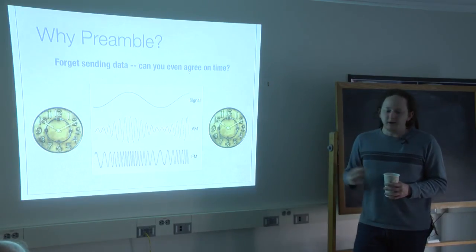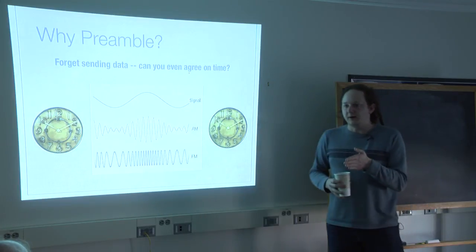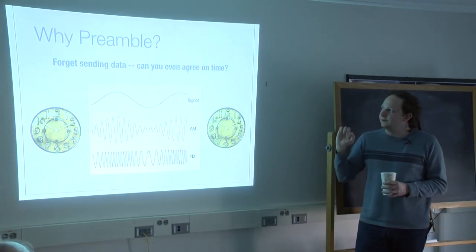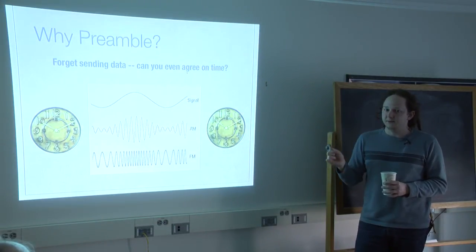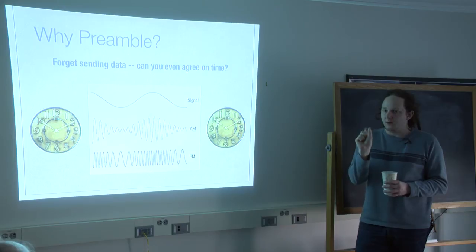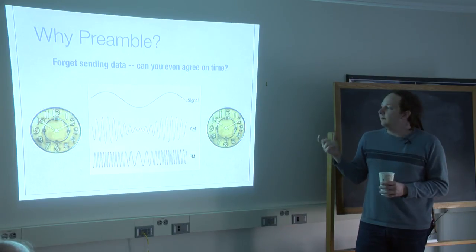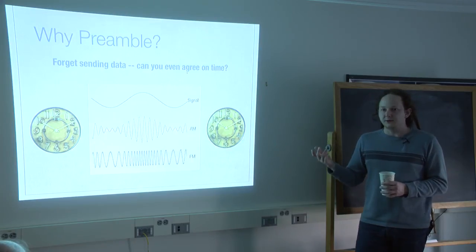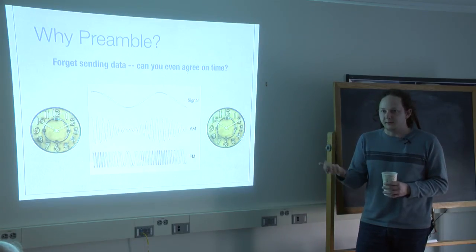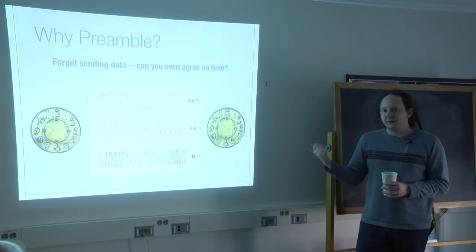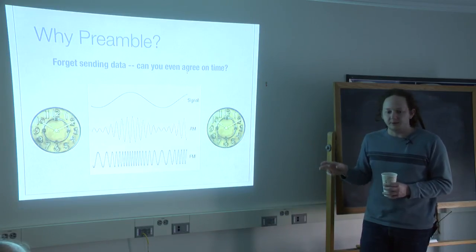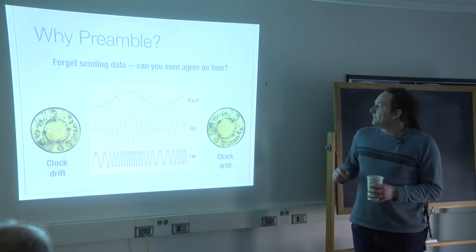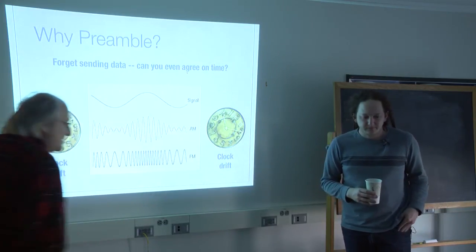The way that they agree on this is that the transmitter and the receiver have separate clocks. And the receiver has a phase locked loop that it trains on the preamble of the transmitter in order to know how wide the bits will be. If you're at low data rates, like 1200 baud audio modem, there's no need to do this, because you can consistently match that with a quartz crystal. But at the higher speeds, you can't do that. You also have variances from temperature. Clocks drift, right? From the point of view of wireless, we're all at sea.